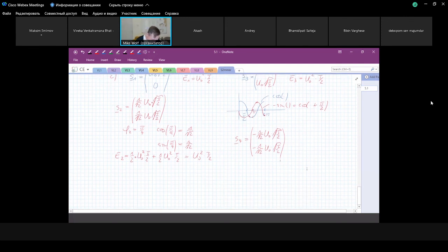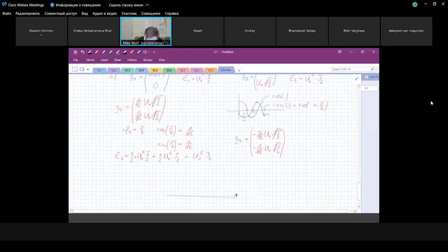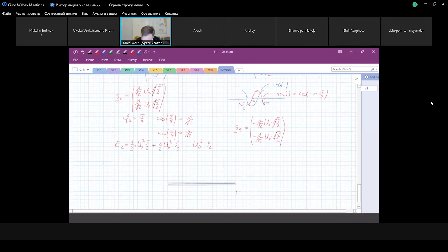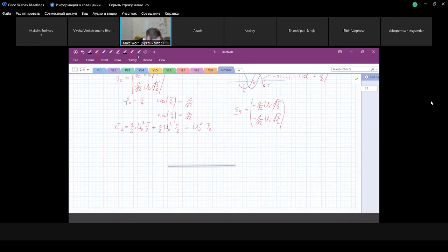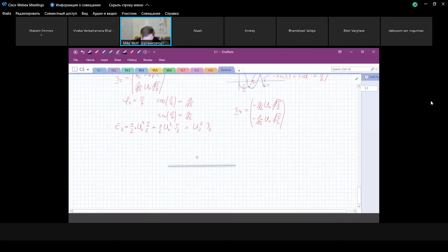And we can draw the signal space diagrams. And we immediately see, of course, that all the signals have the same energy because they have the same amplitudes. And this is a well-known signal space diagram because it's the signal space diagram of phase shift keying. We can encode our information to be transmitted.